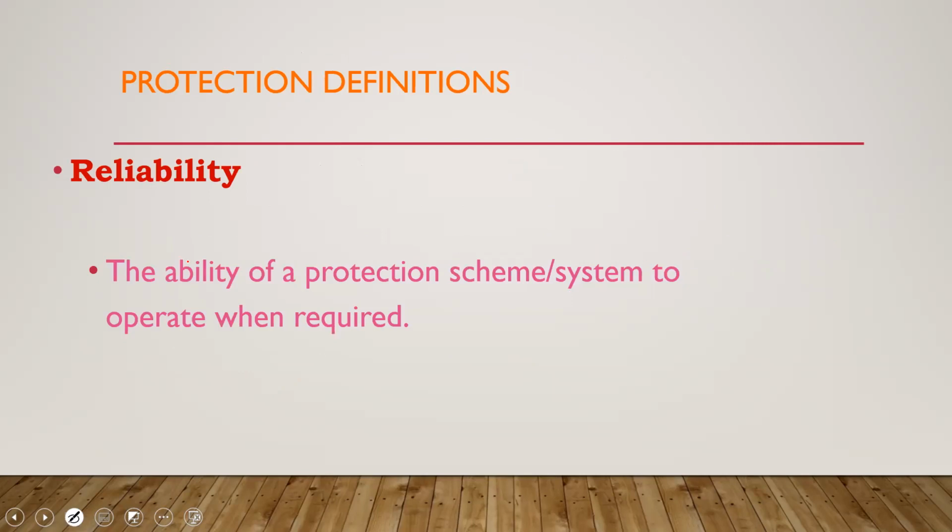So remember I spoke earlier about the breaker and the fact that moisture could have been getting into the panel, the breaker could have corroded, etc. Then when you have a fault, no operation, it means that would be unreliable.